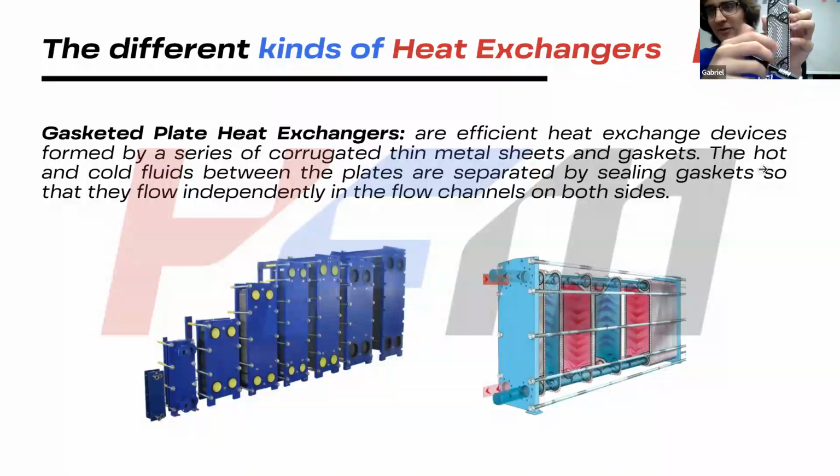Instead, the other fluid is going to go in the opposite direction so that we can optimize the heat exchange. It's going to flow in this plate. And then again, it's alternate. And between these plates, they're going to exchange thermal energy. That's basically how it works. That is basically the principle of a plate heat exchanger, in this case, a gasket plate heat exchanger, because, as I said, it's composed of gaskets as well as the plates. And this is the idea about how we're going to use the temperature management. Maybe it's a little abstract now, but don't worry. Very soon we'll be presenting the images and the examples so that you can better understand the entire process.